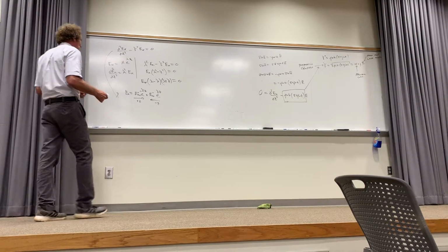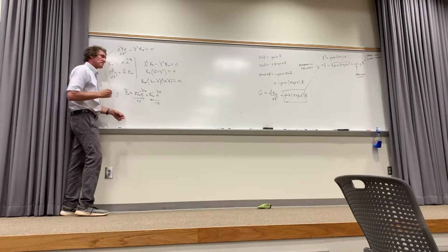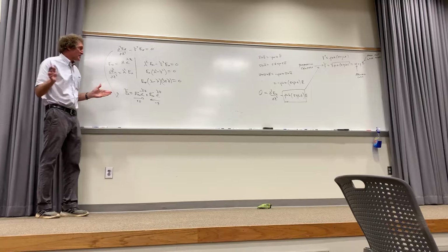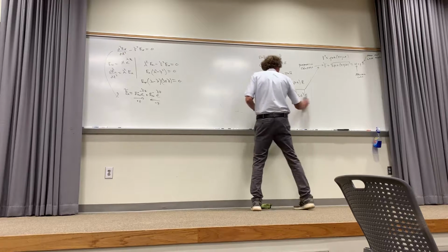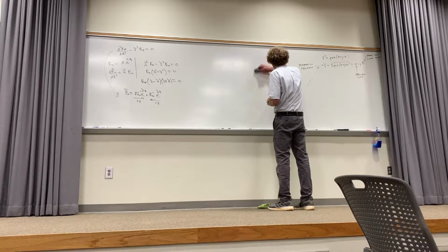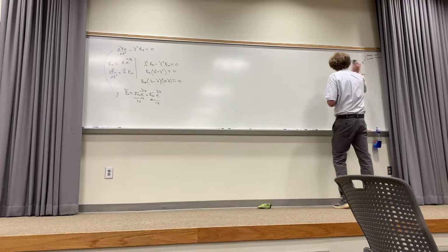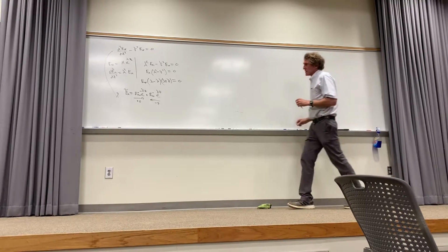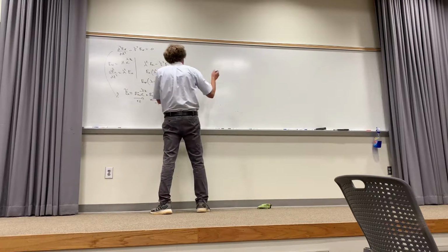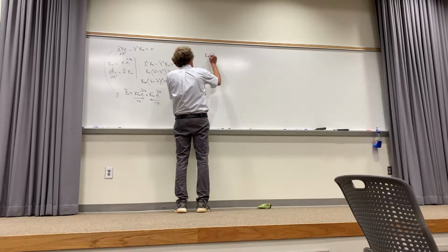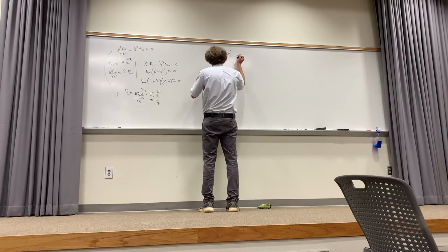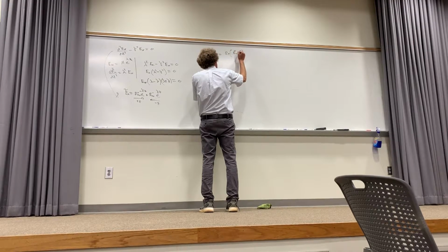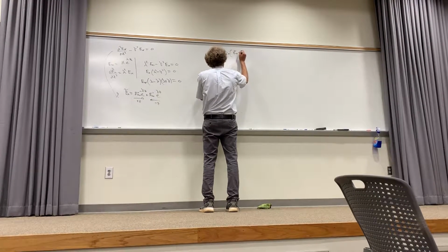All right. Well, this is a phasor quantity. Now, just listen to me. If I want the time domain quantity, the only thing I need to do is take this and, if I want Ex in the time domain as a function of z and t, I take the real part of the phasor domain quantity, Ex tilde, multiplied times e to the j omega t.